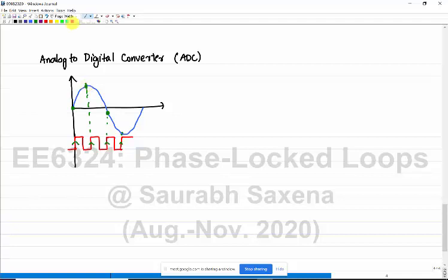Now the important part here is, if your rising edge does not come at the correct point. The first rising edge comes here, let us say this is time period t, and the second rising edge comes at a different time. It does not come at time t, it comes at t plus some delta t. There is some deviation here. Then your sampling point is going to move. And maybe another rising edge comes earlier, then your sampling point moves again.